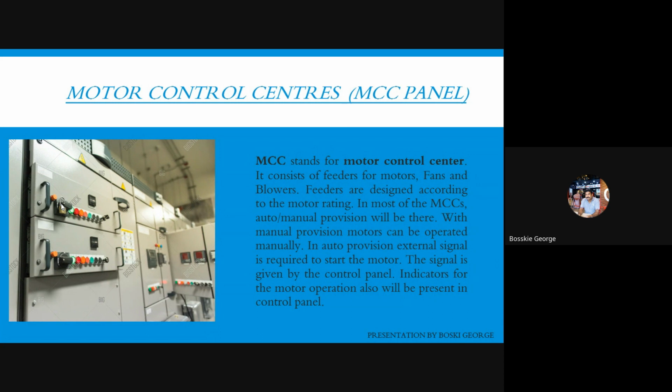In MCC panels there are different types of starters and different criteria for selecting them. We will discuss what the starter will be for a particular application. A VFD is used for a conveyor application, and for centrifugal fans there will be soft starters.